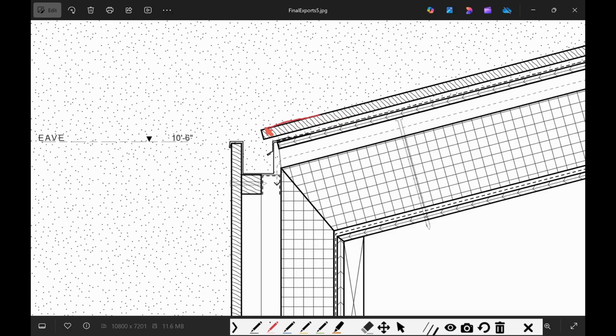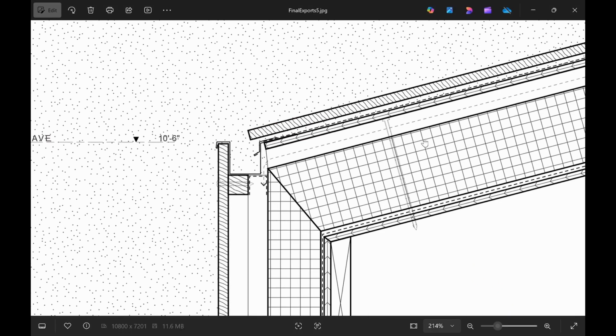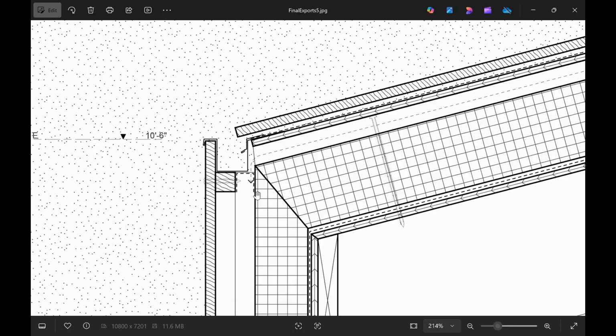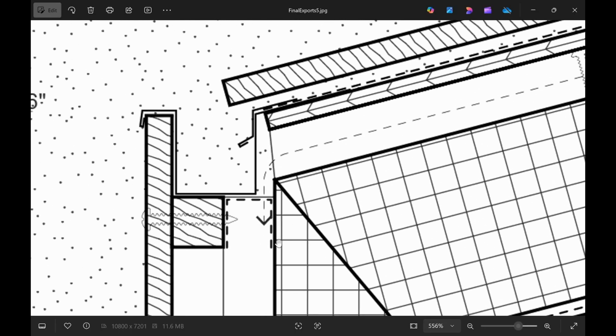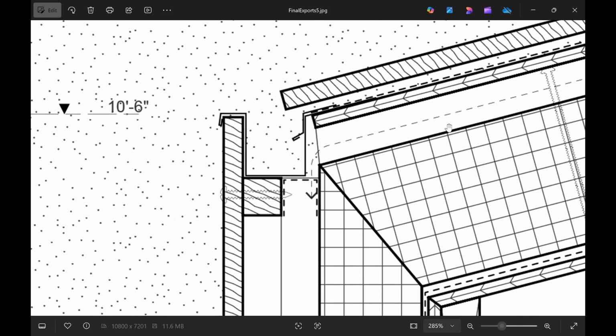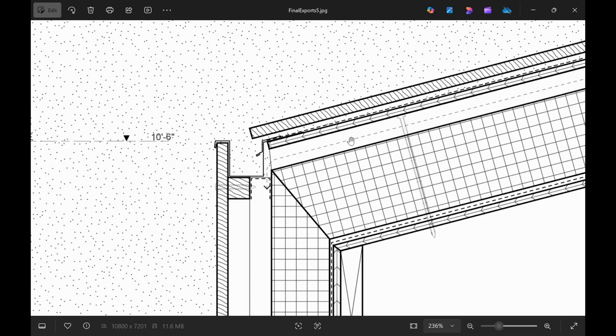If I was going to do it, I would have carried this all the way out, and I would have done either a very long overhang with a drip edge, or a round gutter. Concealed gutters just look really clean, especially for a rain screen roof system. But with a concealed gutter, you would need an airspace and a gap to circulate air. They would call this a warm roof or a hybrid warm cold roof. I'll explain this a little bit more later.